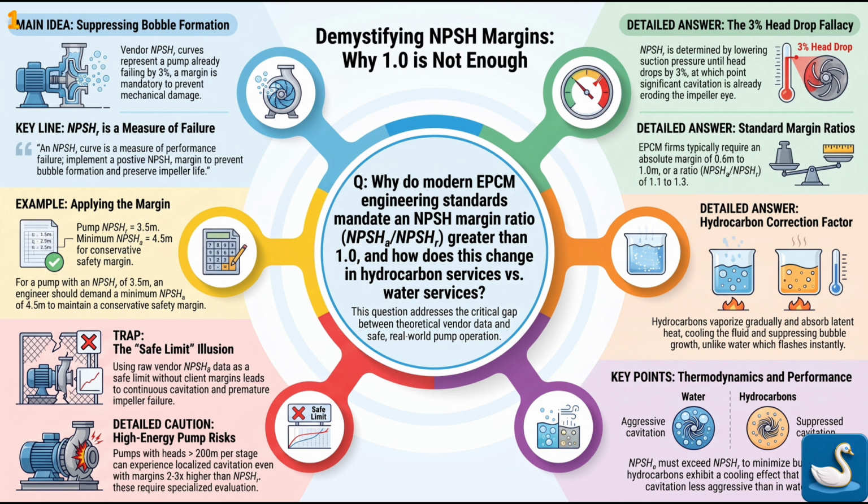That is exactly correct. During a manufacturer's shop test, they determine NPSHR by intentionally choking the suction pressure until the pump's developed head drops by exactly 3%. At that exact mathematical moment, significant cavitation is already occurring deep inside the impeller eye. The process fluid is vaporizing, bubbles are forming, and then as they move into higher pressure zones within the impeller, they violently collapse against the metal surfaces.